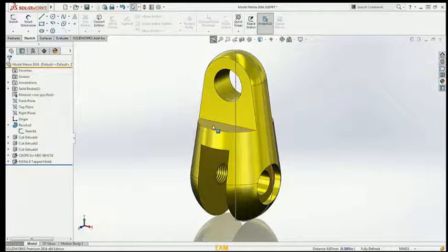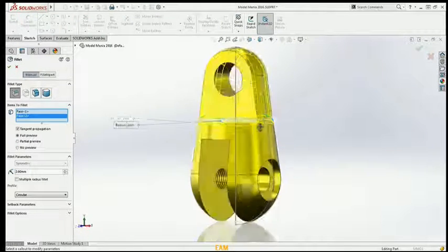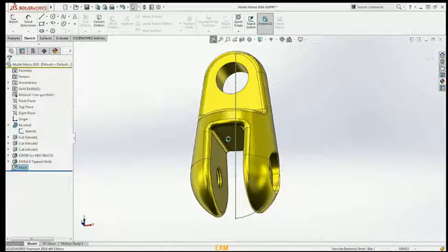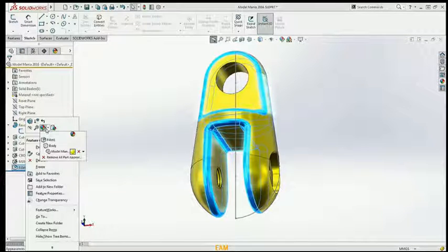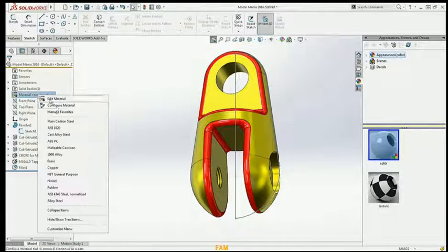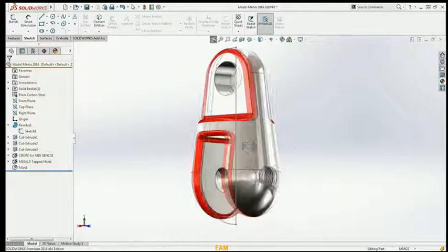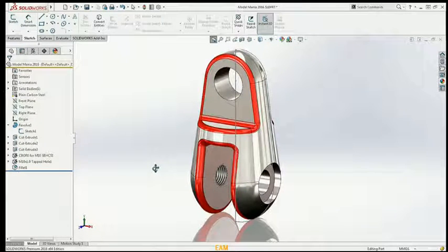This one's just a tapped hole placed onto the planar face, and that's going to be an M10 tapped hole. Add some fillets. I'm just choosing 3 faces. It captures all those edges for me. I don't have to go and select edges individually. It's not necessary, but I like to add color to that fillet. That helps me visualize that, yeah, I got everything covered, and then you got to remember to add your material.